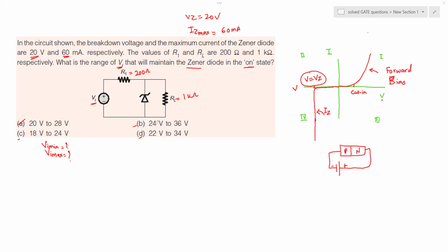So we have to find the optimum range. Okay, so we'll see what range that is. How it actually maintains that, if you have a look at our previous module, we see that I, the current into the circuit, is equal to the current flowing through the Zener and the current flowing through the load, that is IZ plus IL. So how will the circuit maintain the load regulation? First we are talking about the load regulation.